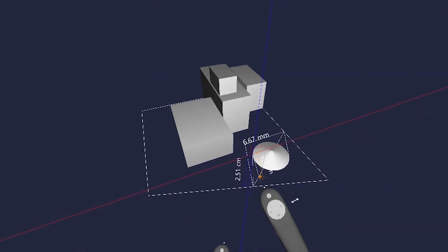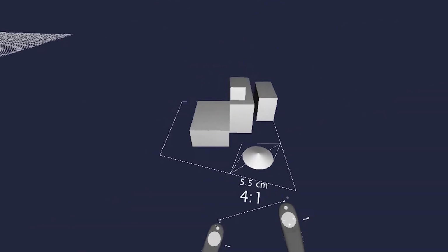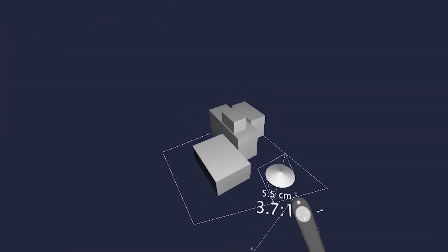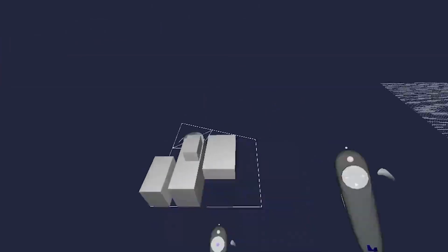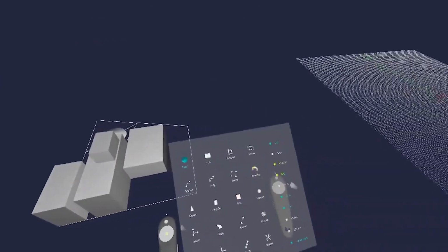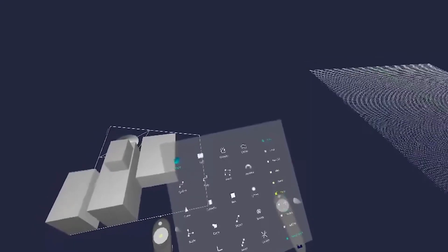It's really important to manage the snaps that are on so that you're not snapping to things that you don't know you're snapping to. You can do this by re-clicking the same teal highlighted snaps.